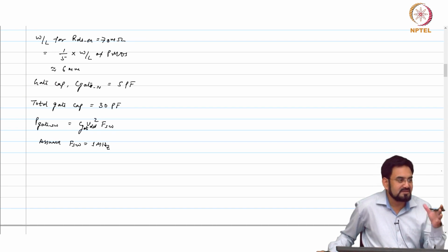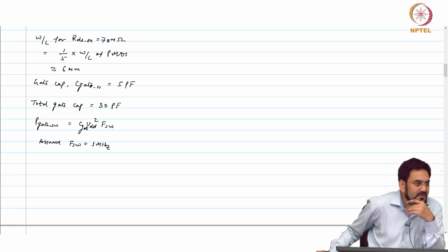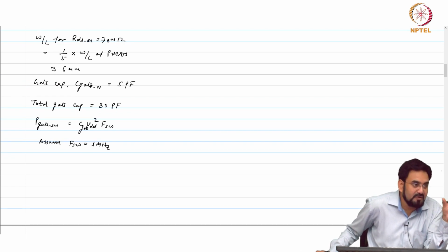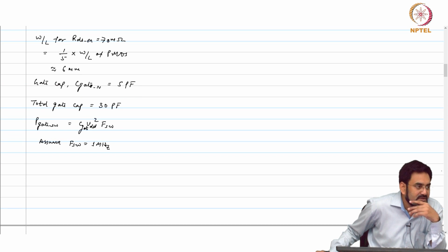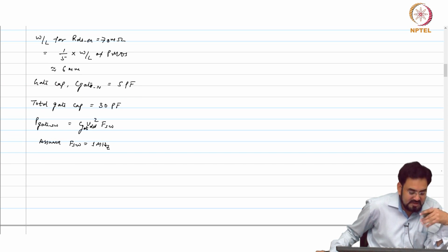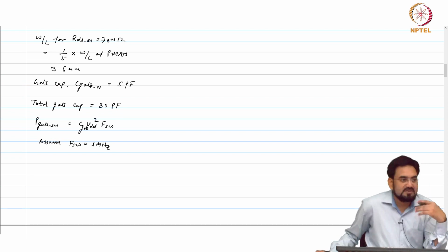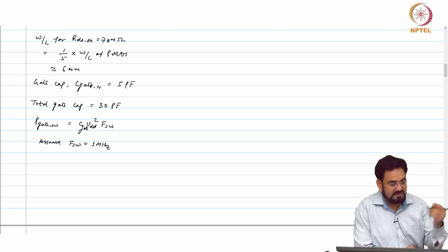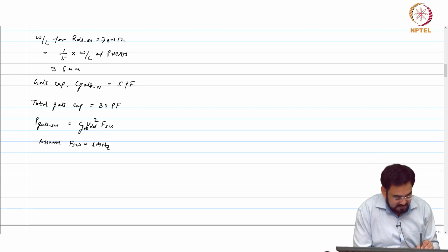So this will roughly tell us what frequency we want to operate at, because at full load we want to keep this switching loss negligible. Okay, so at 1.2 volt and 1 amp, 120 milliwatt was the total loss. So we want to see how much we have switching losses compared to 120 milliwatt, and then we'll decide whether we can have a higher frequency or 1 megahertz basically is the max limit depending upon how much we get.